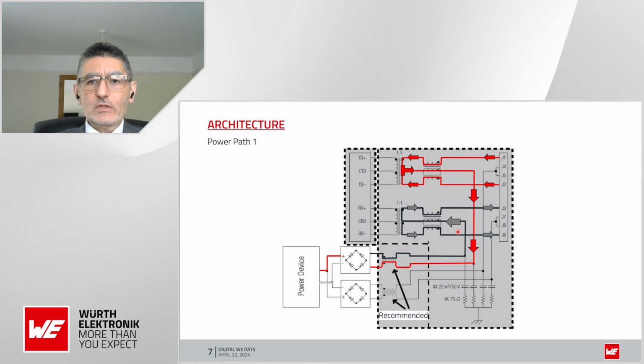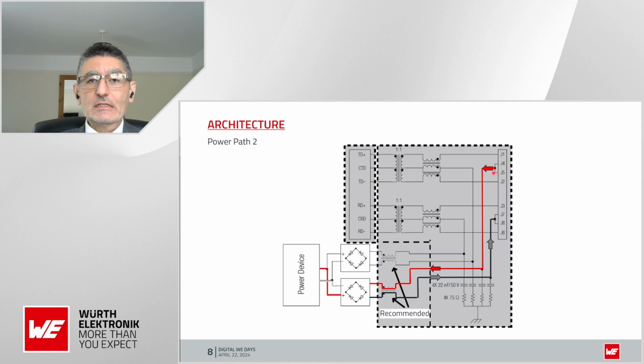So how can we deliver or send power from PSE to PD? In this case, what we're showing is a 10/100 type system. We can either use the data pairs, as you can see there, or we can also optionally use the spare pairs. That's what was called alternative A and alternative B in the IEEE standard, where you could only transfer on either or, and that's for a type 1 and a type 2 PD.